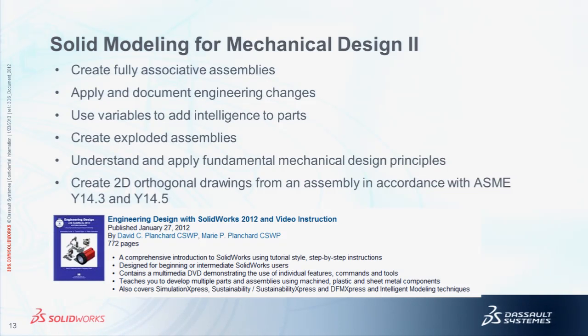So you can make wrong views, put them into different spaces, and then copy those drawings and keep reiterating those things. So if you don't pay attention to ASME standards and how you're projecting views, it's just a downhill process from there. So it's really important that Gary teaches the students, pay attention to this stuff. It's not just put a view wherever you want it.